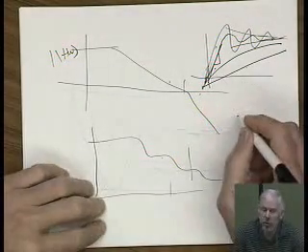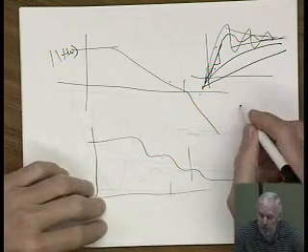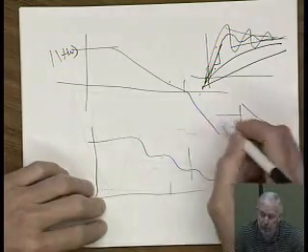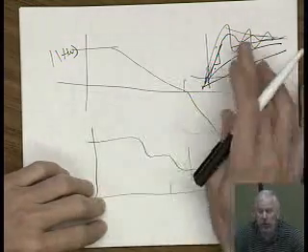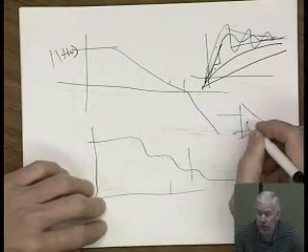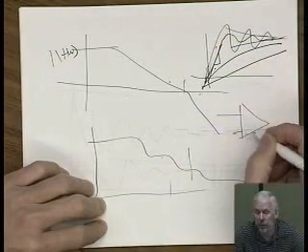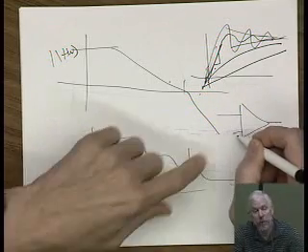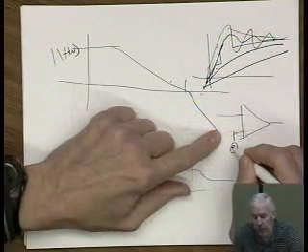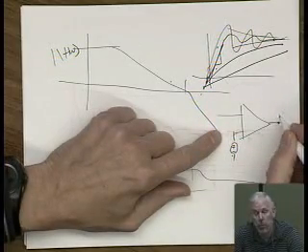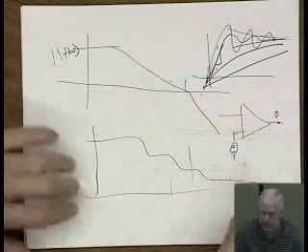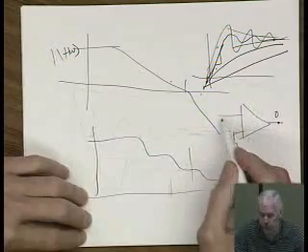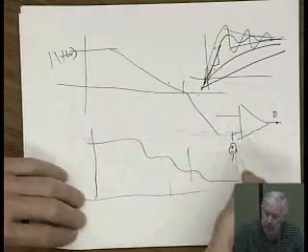The other thing was, when you're doing the open loop response, in the early stages of this, before you close the loop, you're going to be very sensitive, because you have a lot of gain in these circuits, to the offset voltage. This little offset voltage which sets the output to 0 volts. I mean, early on we have this thing open loop.